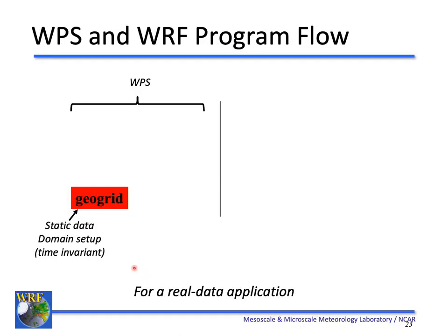Here is a closer look at the WRF pre-processing system and the WRF programs. Program GEOGRID is the program we use to design our simulation domain. And we use it to interpolate terrestrial data onto the model domain. The data processed in GEOGRID is typically used in the model as time invariant fields, for example, topography and land use.